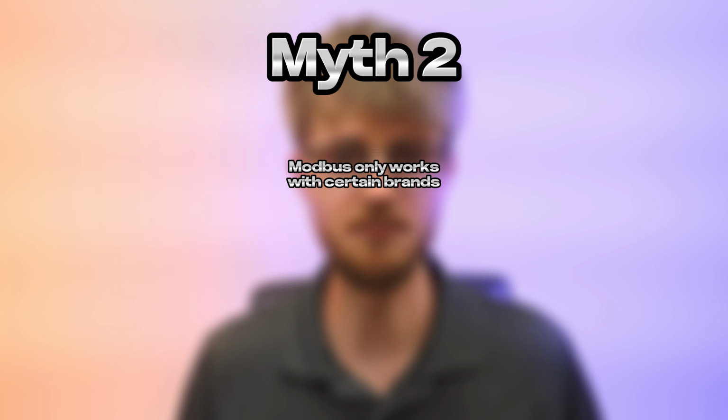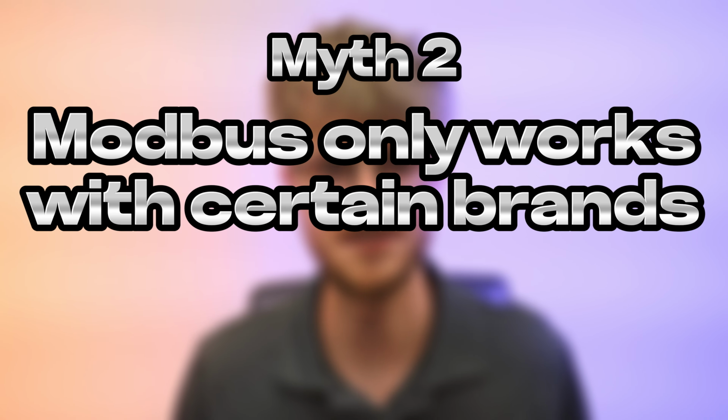Myth number 2: Modbus only works with certain brands. Now, this one could not be more false. In fact, one of the main reasons that Modbus became so popular is because it's open and vendor neutral. Unlike proprietary protocols that lock you into one manufacturer's ecosystem, Modbus was designed from the start to be brand agnostic, meaning any device that supports the Modbus standard can communicate regardless of who made it.